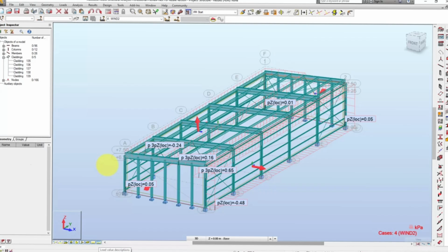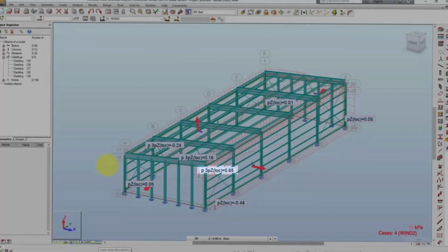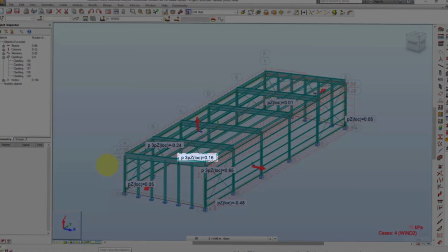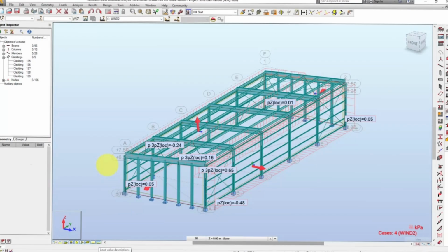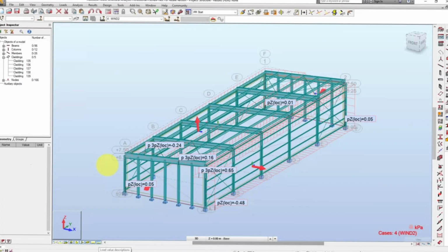Uniform planar loads on contour would need to be defined for the roof as well. Again, defining 3 of the same sections of the roof for the windward 1/6 of the roof. The Z field would be set to 0.65. The adjacent 1/3 of the roof would be set to 0.16, and the remainder of the roof would be set to 0.24. Next, set the live load as the active case.